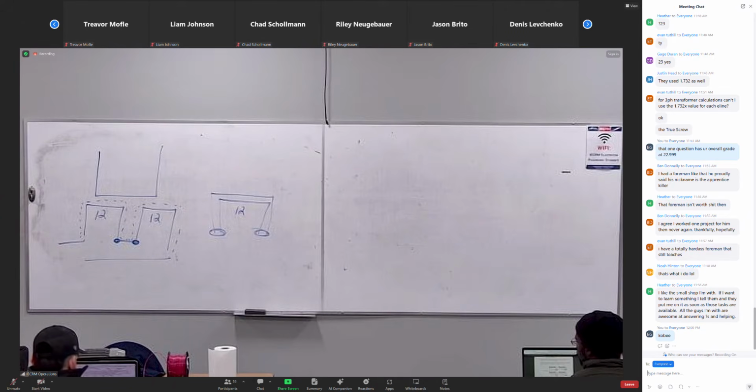So look at 28. Is that the question you wanted, 28? Yes. Okay. So it says, which of the secondary winding connections shown in figure 215.52 is used to connect the proper supply, is correct to supply the proper voltage to the 240 volt load. Slow down. Okay, what is each winding worth on the secondary? It tells you. They're worth what? 120/240. That means each winding's worth what?